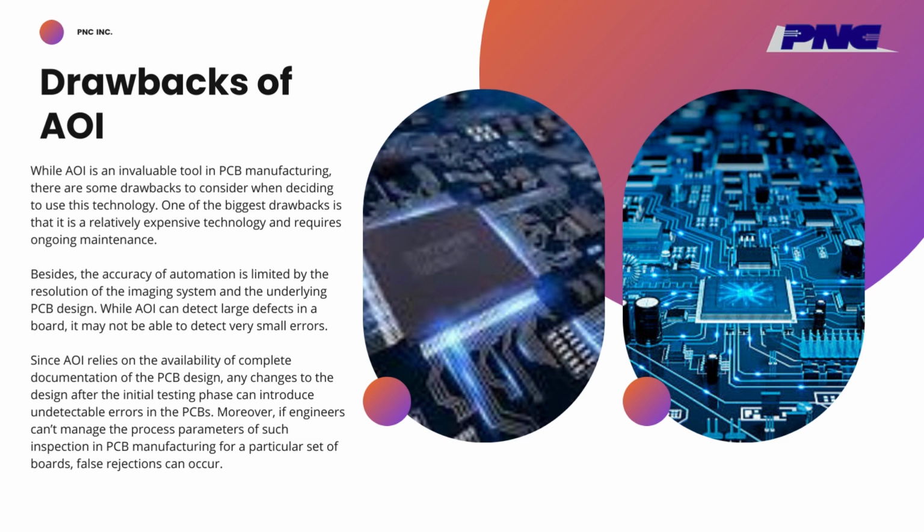Drawbacks of AOI. While AOI is an invaluable tool in PCB manufacturing, there are some drawbacks to consider when deciding to use this technology. One of the biggest drawbacks is that it is a relatively expensive technology and requires ongoing maintenance. Besides, the accuracy of automation is limited by the resolution of the imaging system and the underlying PCB design. While AOI can detect large defects in a board, it may not be able to detect very small errors.